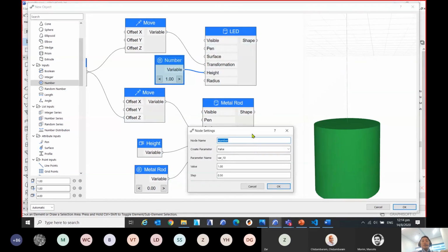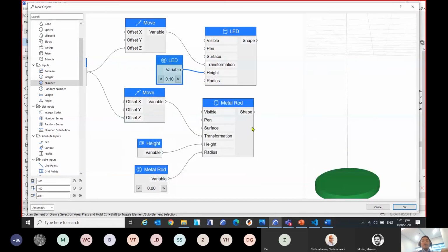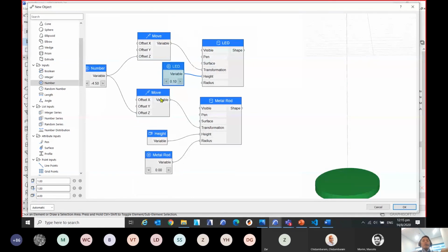Okay, but this time I'm gonna use this one as my custom parameter, so I need to name it properly. So click this one as true, and I'll copy this name and place it here as parameter name and type in the height. Okay, we check, maybe the value is around 100 mm and I click OK. Yep, that's the height I wanted.